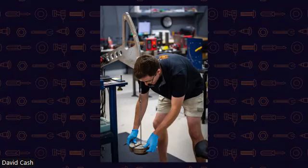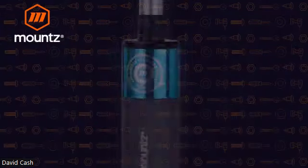And so as weight is applied at a certain distance, the resistance value of that sensor is giving us a value, and then that value is correlated to the particular amount of weight that is on the analyzer. And so this is done at several points throughout the range of the actual sensor. And that's how we use the static reaction type sensor to measure the torque that is being generated.